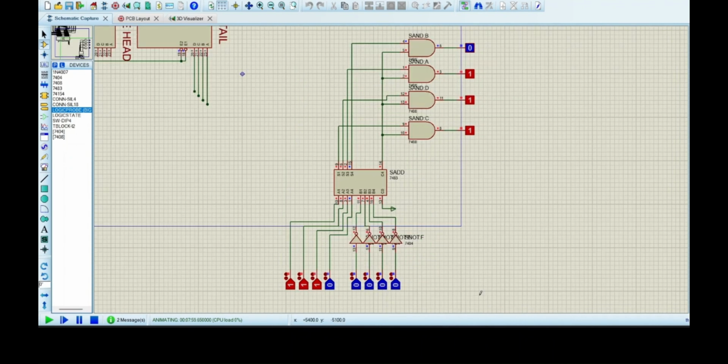We have added a similar feature, which is that the snake bottom never goes below 0. This is done by using carryout from the subtractor of the snake position decoder module. When we get a negative number, we get 0 from carryout, which is connected to the snake tail through AND gates, which give 0000 position of snake tail when the sum is negative.